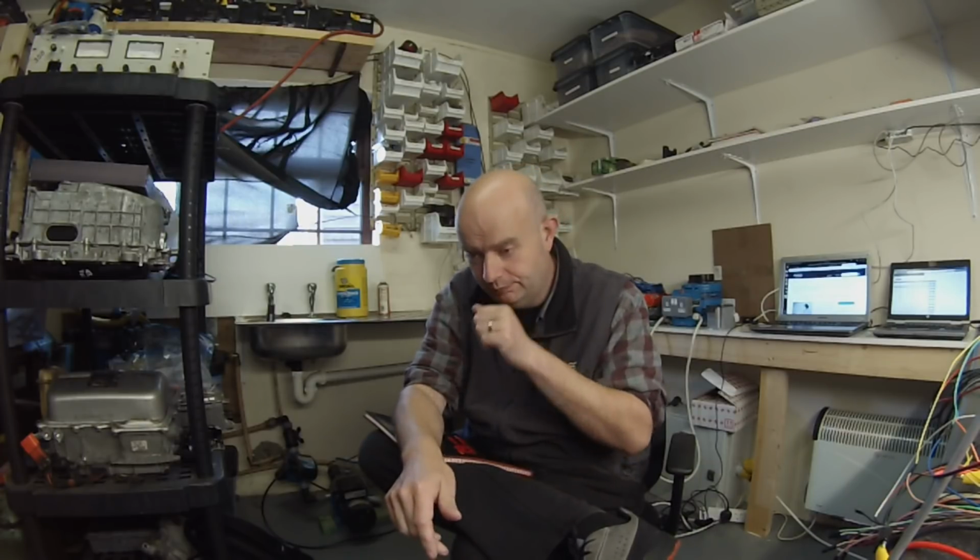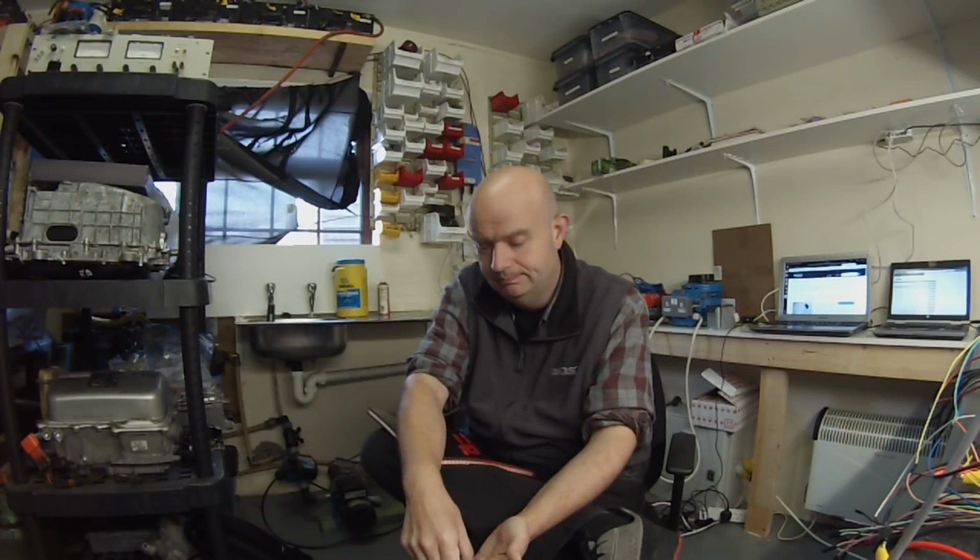Sorry, I should clarify. Trip mode comes into play when an overcurrent event is detected by the hardware overcurrent detection circuit, and it basically tells the microprocessor what to do when it gets a hardware overcurrent detection.